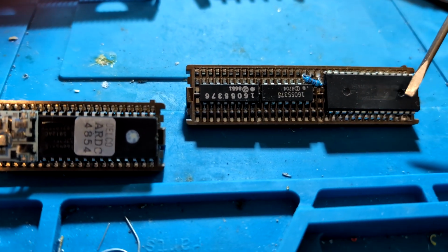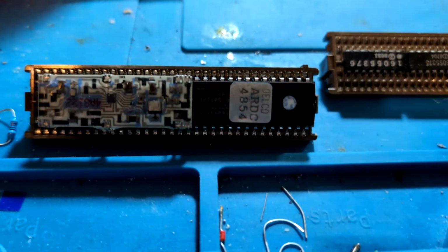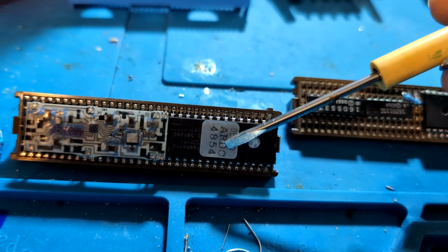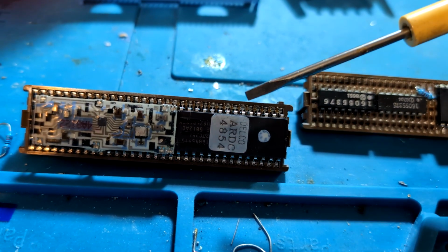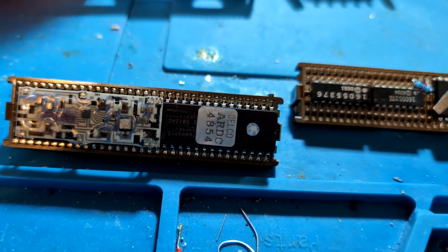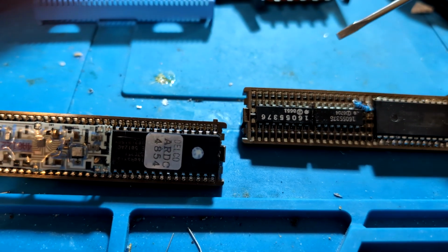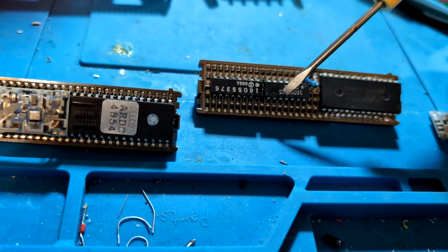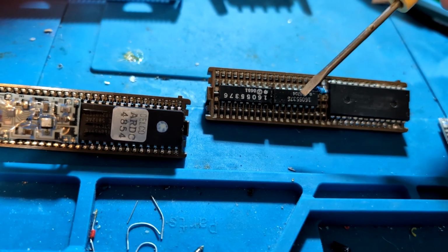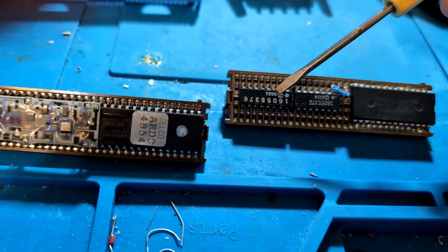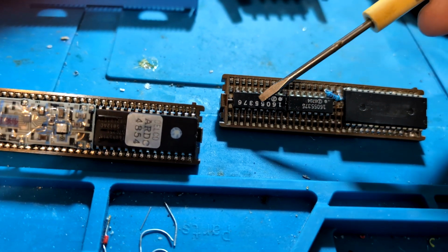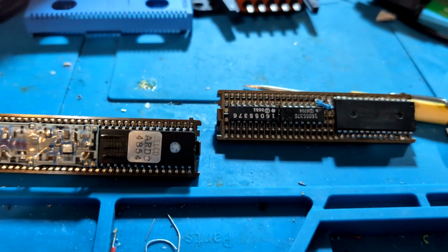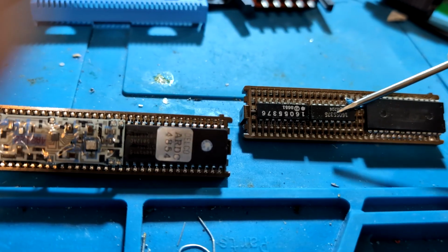If something was to go wrong with your EEPROM, and the program inside here became corrupted, in theory you would still be able to drive your car home. It would still drive very poorly, but it would drive on these sort of analog chips, which would still fire your injectors and give you basic rudimentary ignition timing control in your engine. That's kind of the idea behind these chips.